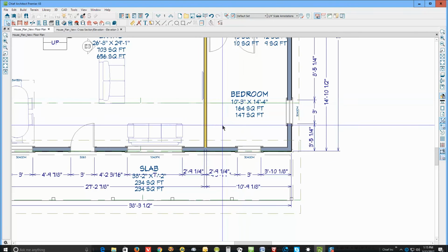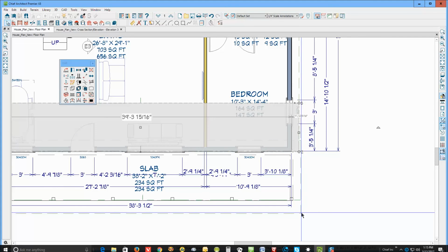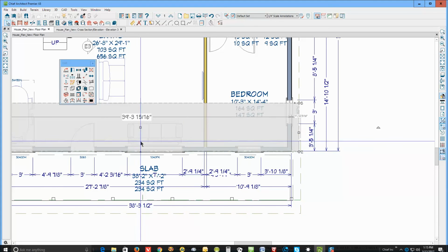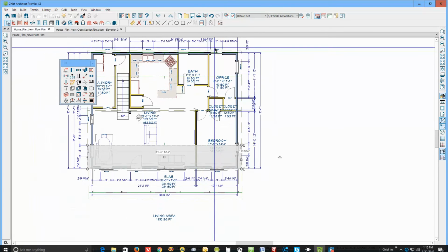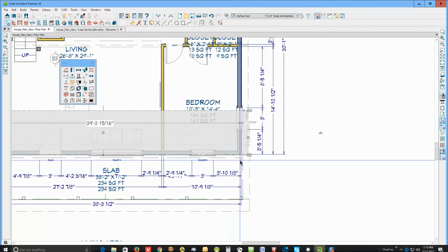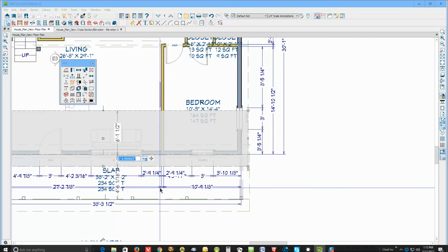And I'm going to check the next roof planes. Yeah, it looks like that baseline's in the right place. I'm just checking. Now we need more overhang. So you got almost no overhang, so I'm going to just jerk this down. And we'll set it to 6 inches. You could probably set it to less than that, but 6 inches, I'm just going to use that arbitrarily.